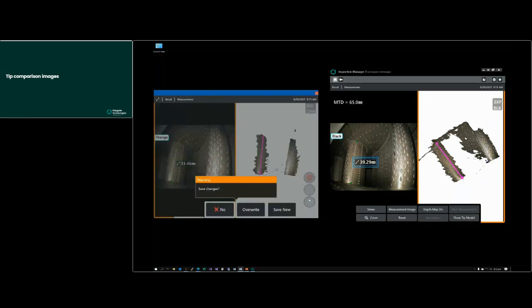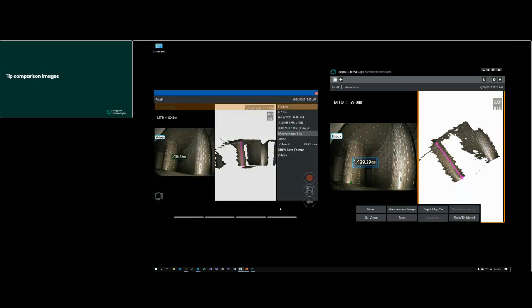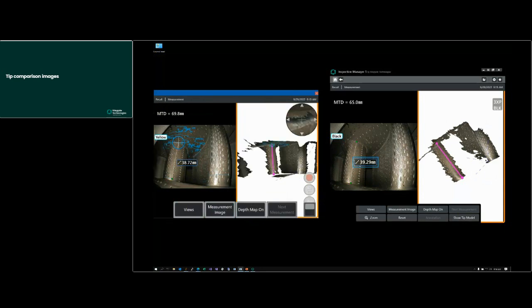So if we switch now over to the yellow tip on the left side here, you can see that we get even more data than we have with the black tip. So going back quite a bit further on this vane and in the top area. And the noise levels are significantly lower as well with that yellow tip. So that optical brightness difference, that 60% increase, does give this yellow tip some enhanced capabilities, even though it's mechanically the same projection geometry.